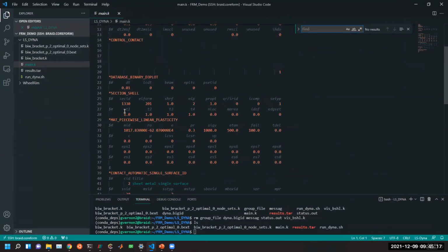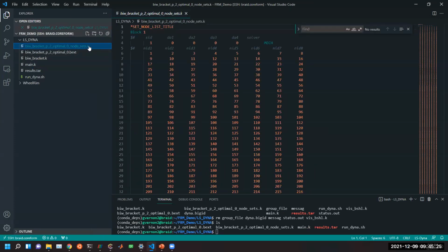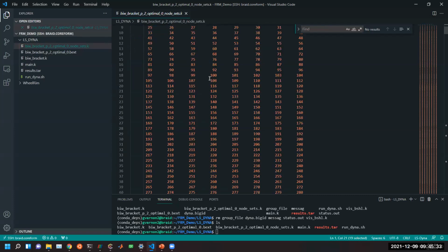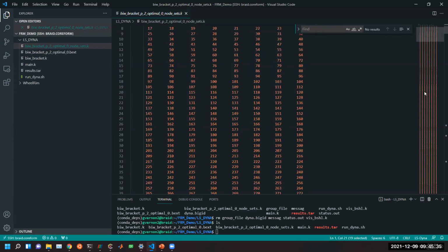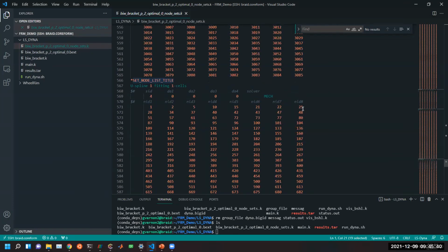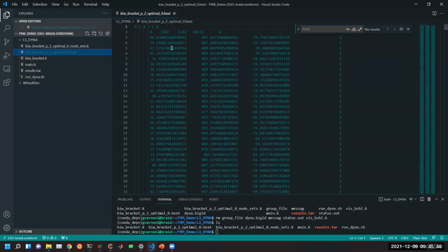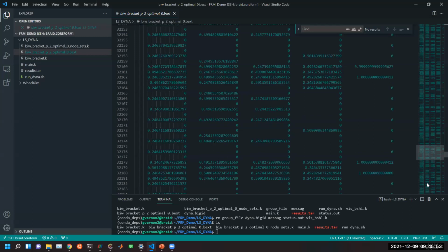For time's sake and performance, what we're going to be getting is a BEXT output file. The DYNA cards option will also export several node set K files that will define lists of node sets that you'll need to include in your model. And they will have names for the different kinds of cells that they have, like side set 3, for instance. It'll also spit out this BEXT file, version 2.0, that LS-DYNA can parse.